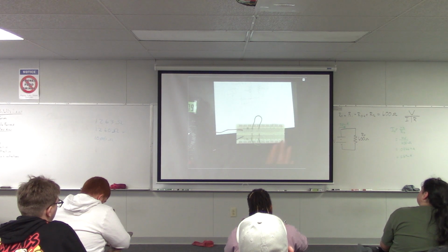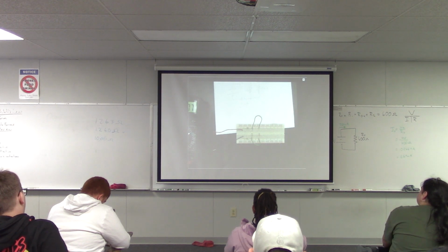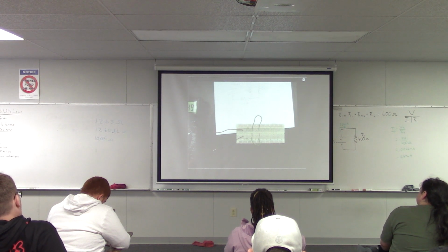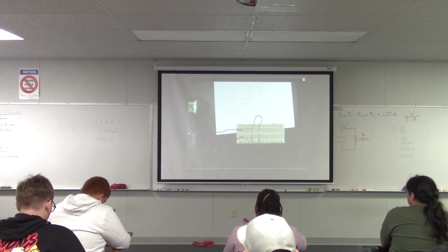Again, you need to have the power supply hooked up when you're making those voltage measurements, because the power supply provides the voltage to your circuit. So, questions about measuring voltage?